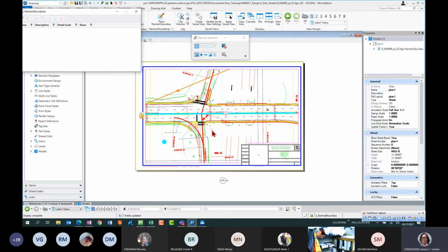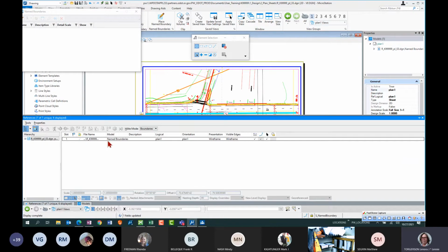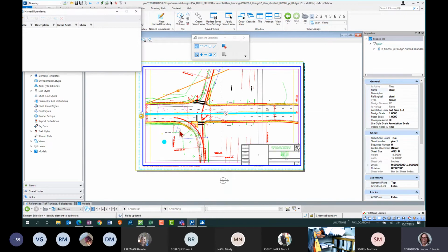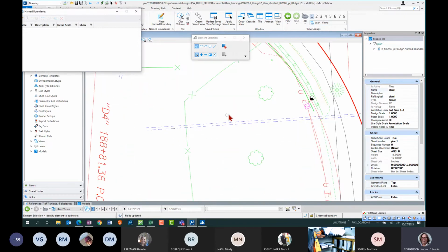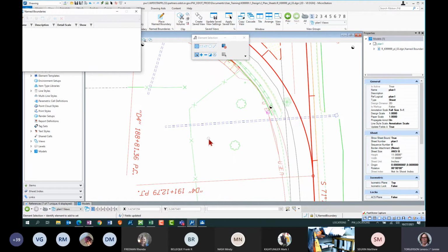It should. If yours is also not picking up the default attachment settings, they can be fixed individually after we place the reference by selecting the reference and toggling off the scale line styles. It's not something I'd want to do if I was using open roads to cut 100 sheets. I don't want to go into 100 sheets. So I will investigate that and figure out why that's not working the way I want it to. But this is how you would do it today.